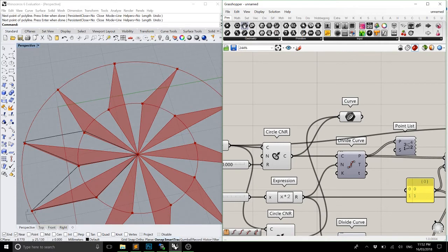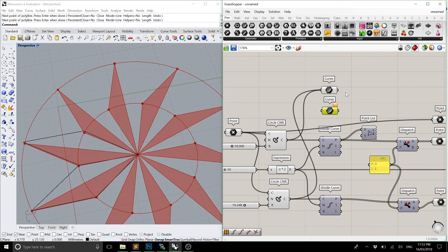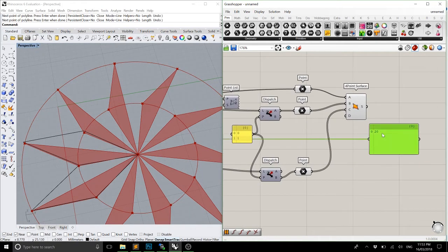One more little trick is if you have another component that you would rather these wires be plugged into, and let's say you might have 100 plugged in here, you would otherwise have to plug your 100 in again. Instead of doing that, you can hold Control Shift, and that will pull the wires out of the component you select them from, and allow you to plug them into the new component. So those are some wire tricks there.